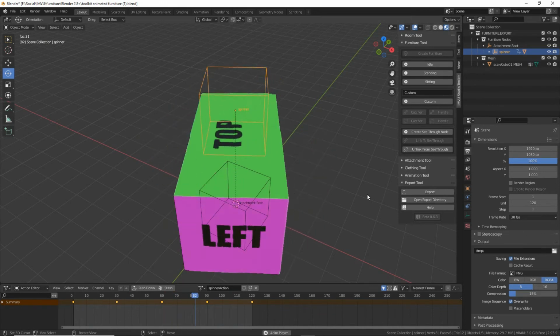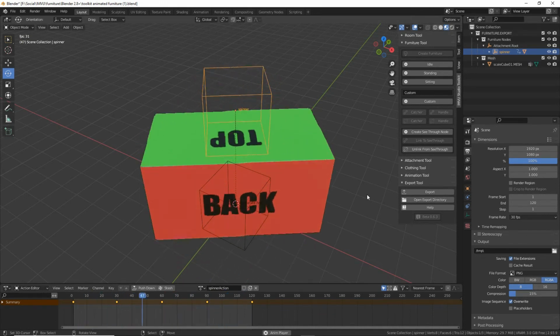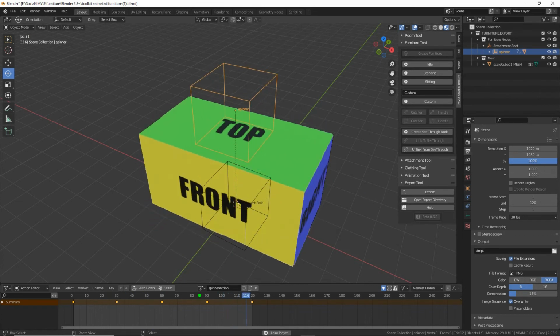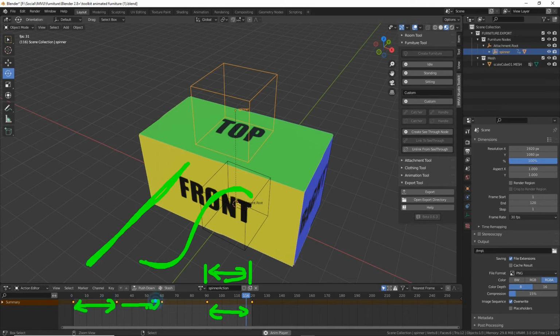It slows down and it pauses because the interpolation, that is how the in-between frames are interpreted keyframe to keyframe, is a Bezier curve, which means as the sequence eases from end to end. What we want is a uniform rate of change, so that would mean that the distance between the frames is the same regardless as to whether it's in the middle or at the end transitioning to the beginning again.